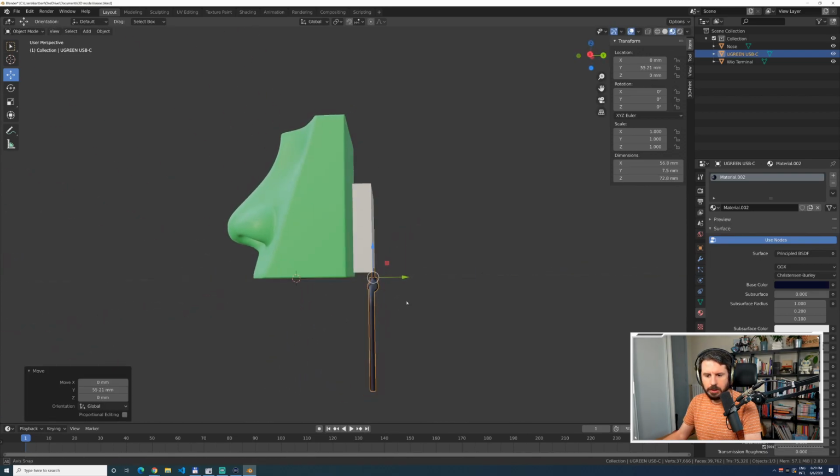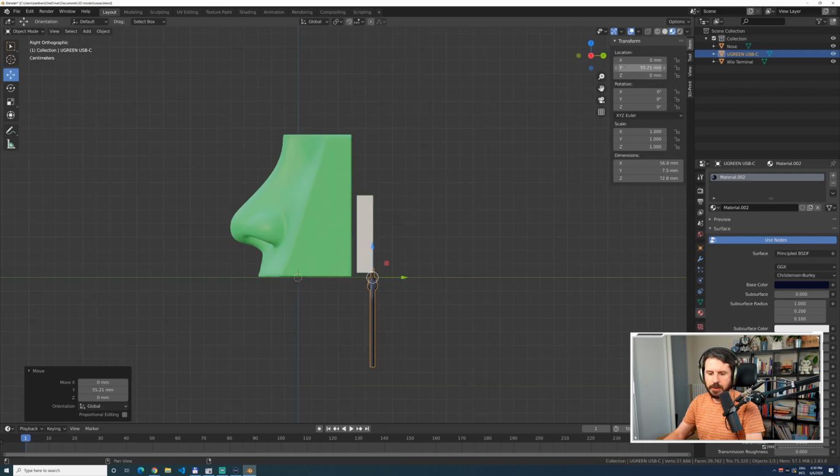Where are we now? Yeah, one thing that I also should be doing is using the shortcuts for rotating the view. That's 1, 3, 7 on the numerical pad, which allows me to quickly switch to go left, back, and top, which is quite convenient.